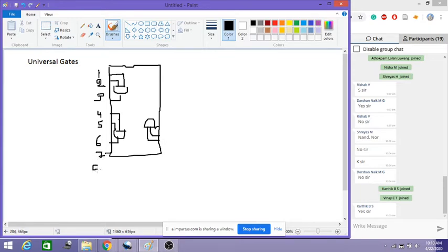This will be the ground point, GND. And this is pin number 8 and 9, and the 10 might be the output. So likewise we have one more here, this is 11 12 and 13 might be output, and pin number 14 is VCC for this IC.